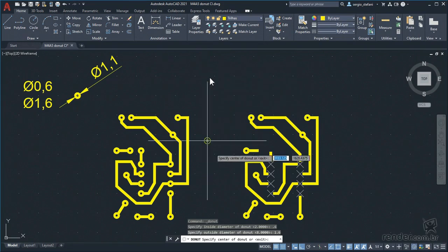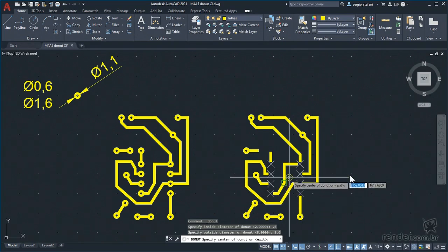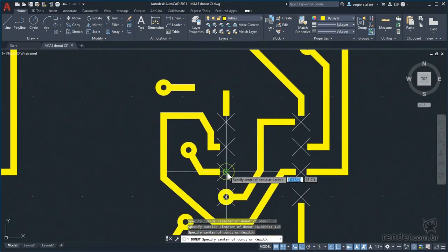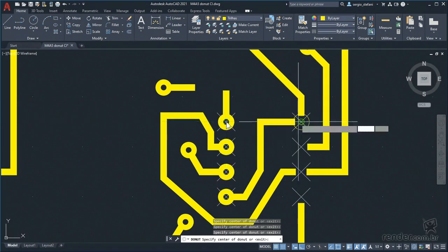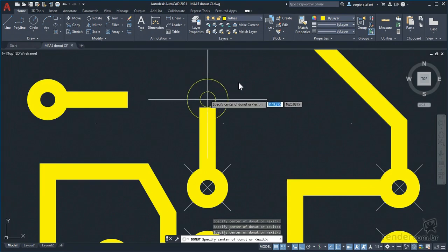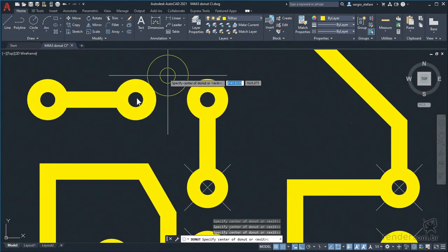Now let's use the node precision tool to capture these points, which will make it easier to locate donuts. We zoom in to make it easier and we will click on the sequence as shown. See that the task is very quick to do. Finally, let's do these other two. See that there are no predefined points here. Let's get the drawing closer. And with the snap active, which its value is already set, we will position the two donuts as shown, and that's ready. Enter to exit the command.